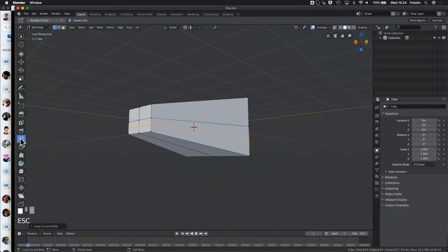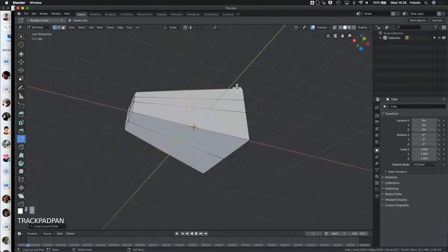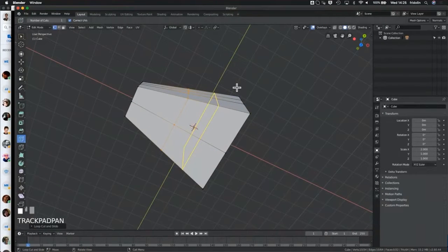So to do that, let me show you again. You go over to the left here, and you click Loop Cut. It's that one. It looks like a cube being cut in half by a green band. So you select that, and then click on your object in edit mode where you want to, or the kind of direction and plane that you wish to do the cut in. And then by dragging, you can state where it should be. And that can also be achieved with typing in numbers, of course. So the loop cut's a really, really useful tool for working with meshes. It allows you to start with a really simple mesh that's only got 8 vertices, and very, very quickly increase them, and not just uniformly increase them in places of interest.